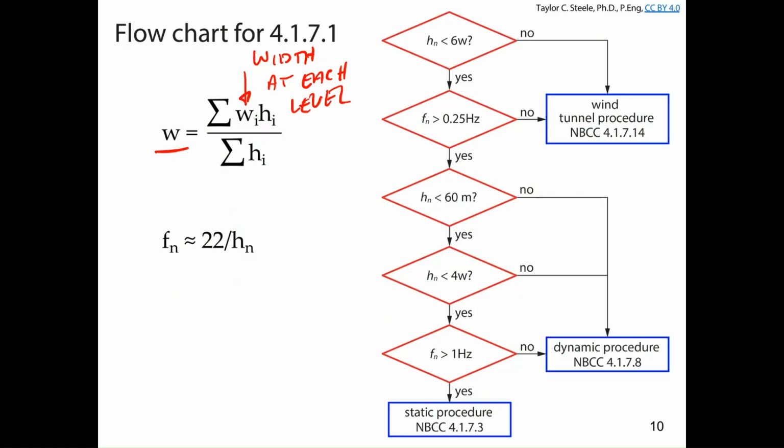And if it is, are we looking at a new fundamental frequency here being greater than or equal to 1 hertz? Okay, so I've got a taller structure here. I'm going to do my best to pull it to vibrate back and forth. And I was trying to measure the frequency earlier today. If you were to count, for example, I might say 5 cycles. So I might pull it to here. 1, 2, 3, 4, 5. It's about 1 hertz. It's about 5 cycles in 5 seconds. And so in this case, for the taller structure, our fundamental frequency is 1 hertz.